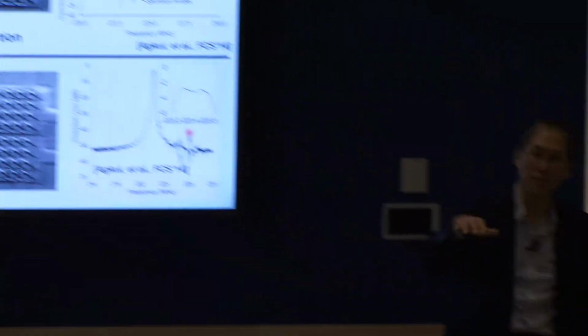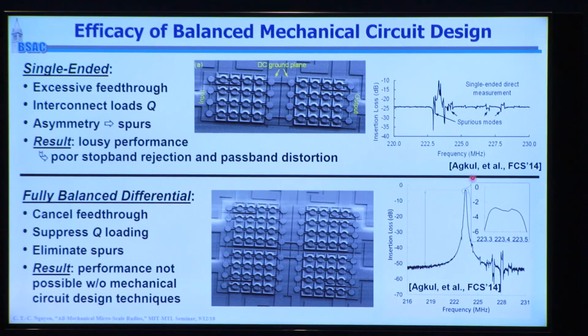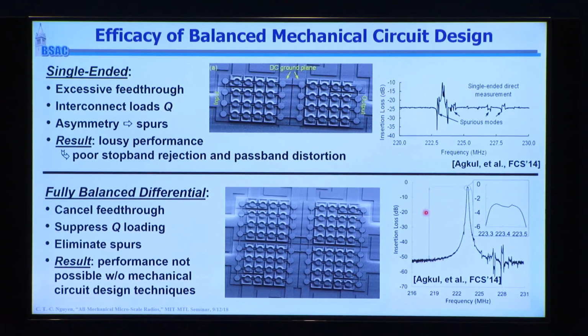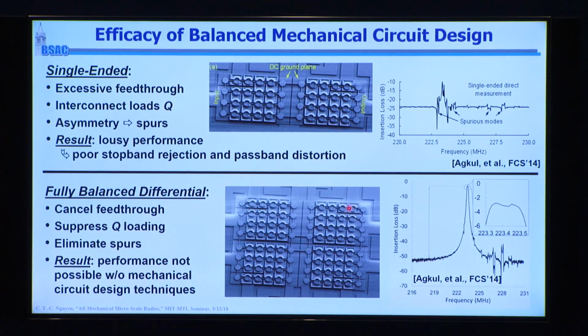because they have a formula for killing off spurious modes. That's why, if you've seen an FBAR filter, they have these polygonal shapes. Those shapes are there to knock out the spurious modes. And that's what all the competitors are trying to do. They're trying to kill the spurious modes. Well, this kills the spurious modes just through balancing. Okay, very nicely here. So it's a nice filter technology. And on top of that, it is a channel select filter technology that you can get because our Qs are so high in this technology.